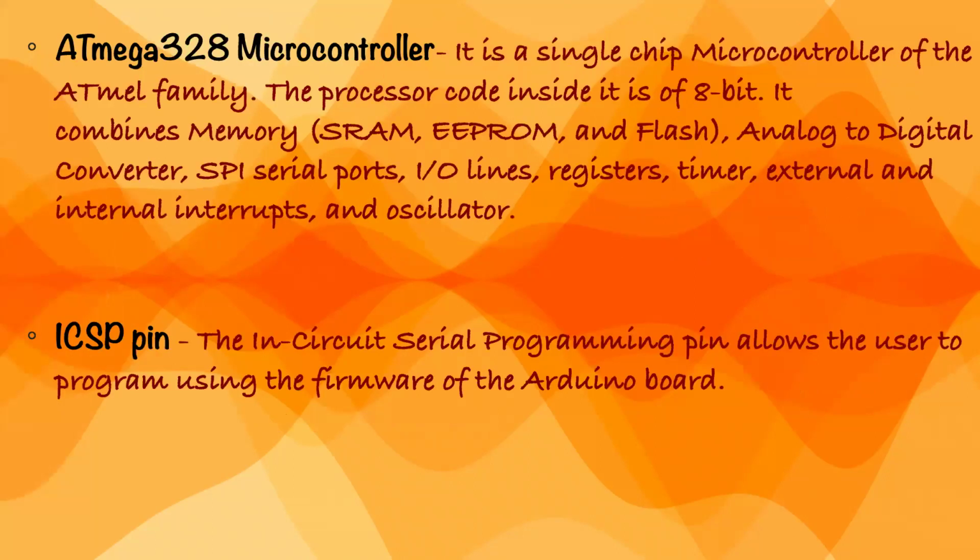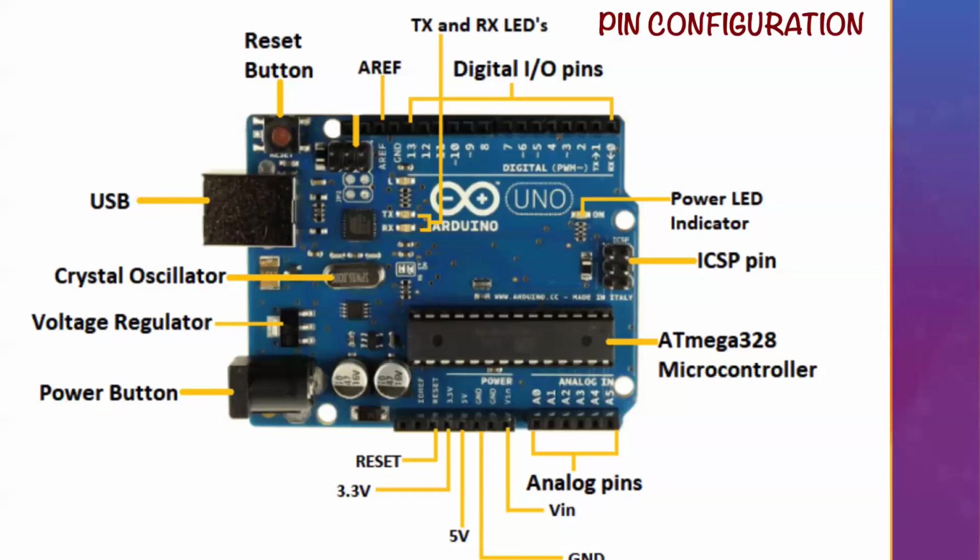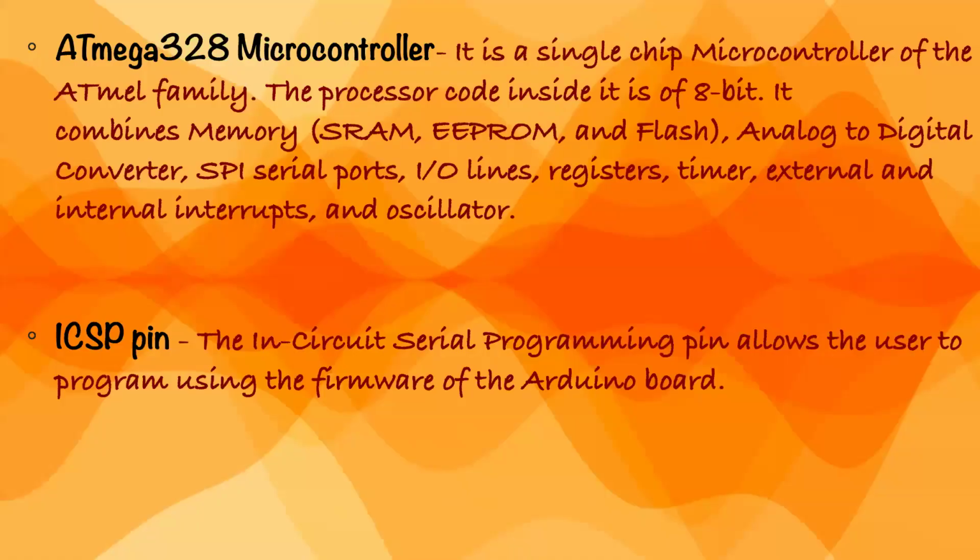If you see here in the diagram, on the right side it says ON, and there is a very small LED over here. So this is the power LED. Whenever you connect the laptop or computer via the USB over here, it receives power and it will glow. Or whenever you remove the USB but connect a power supply here to run the Arduino, it will show as well.